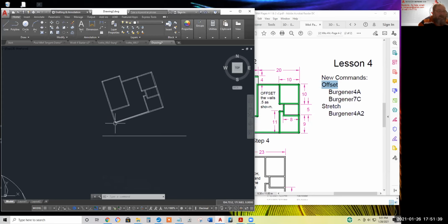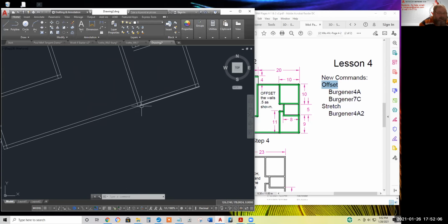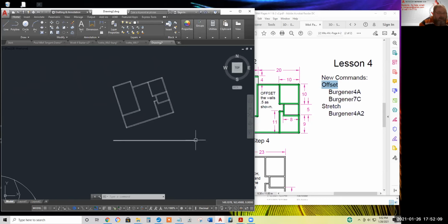The bungee cord is infinitely strong. It'll shrink down to 0 length. The second one is weaker, and for 3D work, the third one is weaker. So the second one, I'll pick any one of these endpoints or a midpoint and select this as the destination point. So whichever point on this outer wall here I select will get as close to this endpoint as possible, which will flop it literally on this guideline.